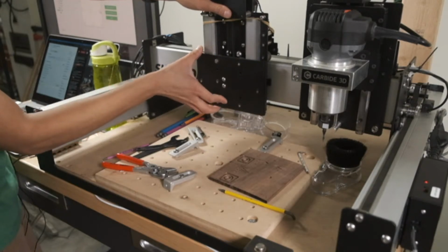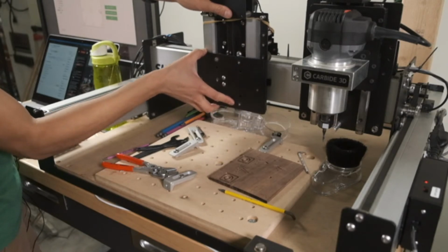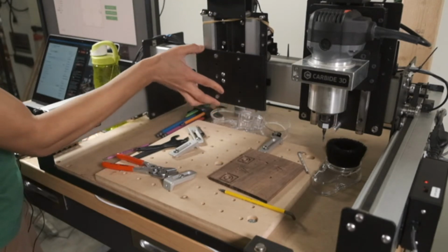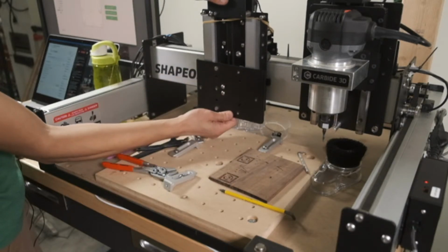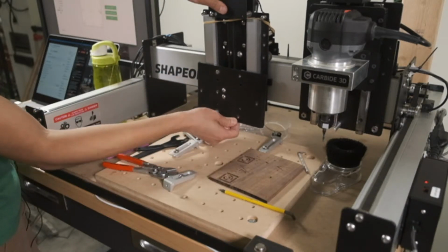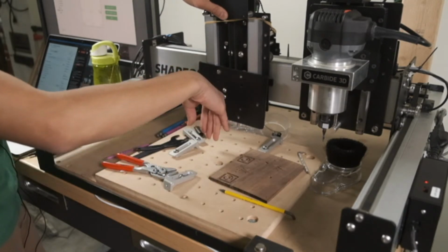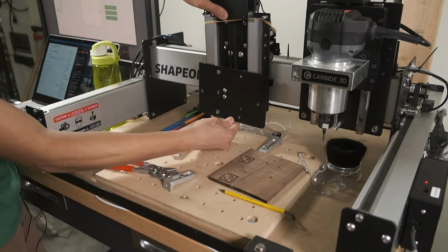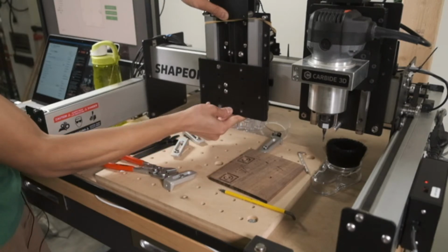I believe we have it so that you can't jog too far past this, but if you're not careful, it is possible to have the bottom of the carriage plate, the V-wheels, come off the rails, and if so, that's another place where you can get wild movement in the spindle and lose your accuracy or the definition of the features you're trying to cut.